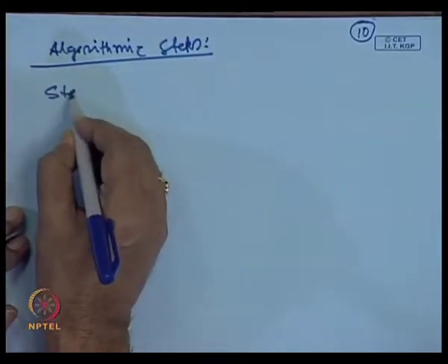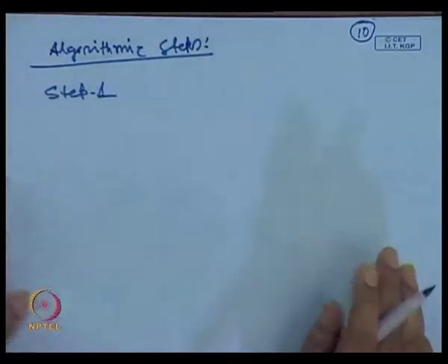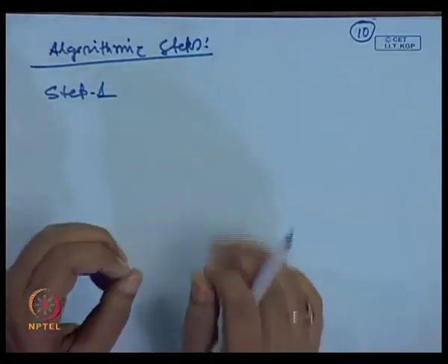So, step 1, in this method we will just find out the eigenvectors of the matrix H m corresponding to stable eigenvalues mu 1, mu 2, up to mu n, that is the method only. Once you know the eigenvectors, we know how to find the solution of the Riccati equation P. That means the first n rows we pick up and form V 1, V 2, V 3, up to V n, and this is nothing but the eigenvector corresponding to the closed loop system eigenvalues.